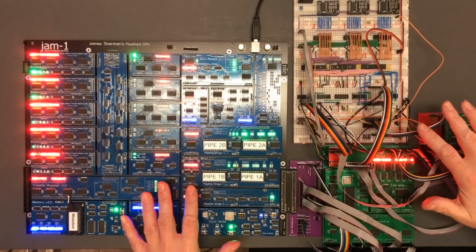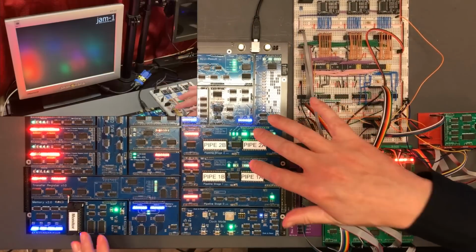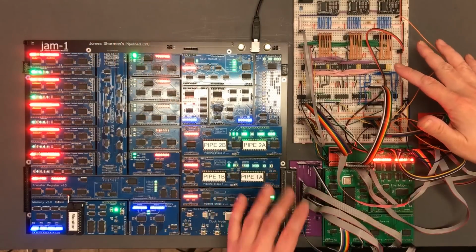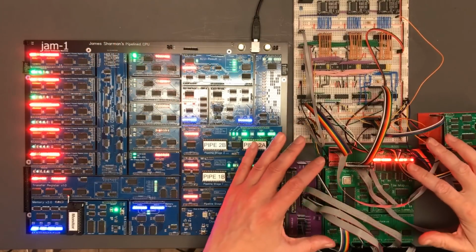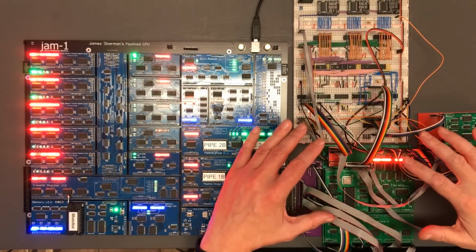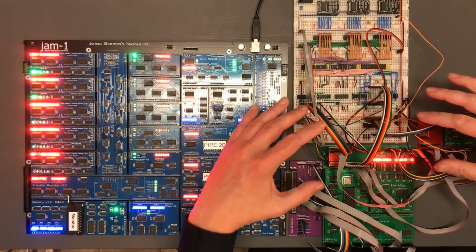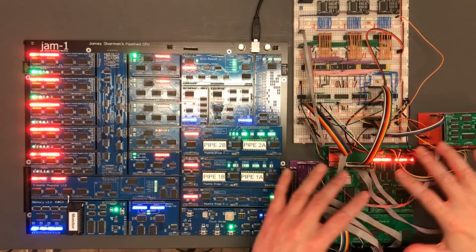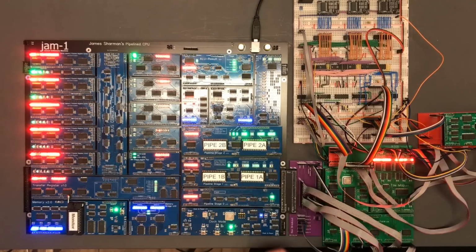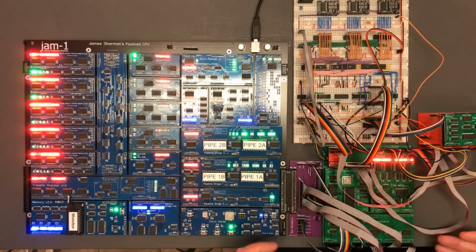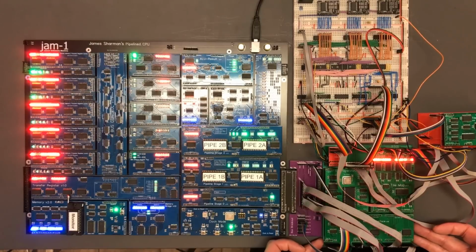Right, so I've got the build powered up and the monitor ROM is outputting our basic logo here, which shows us the VGA is working. Now this big mess of wires here is the thing we're really worried about. The connections into the breadboards, we obviously need all of those, but I do think we can do something about all of these connections down here. We've got all of these connections from the bus breakout down into this VGA module.